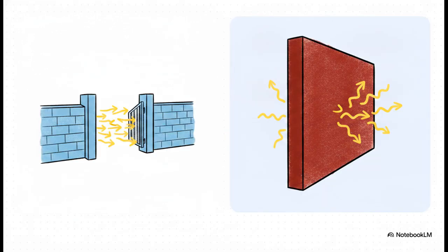But here's where it gets incredibly cool. The real power comes from actively controlling that wall. Applying a forward bias voltage actually shrinks the depletion layer, letting current flow freely. Flipping it to a reverse bias drops the voltage across the depletion region, which raises the wall and totally blocks the current. It's basically a microscopic traffic cop.